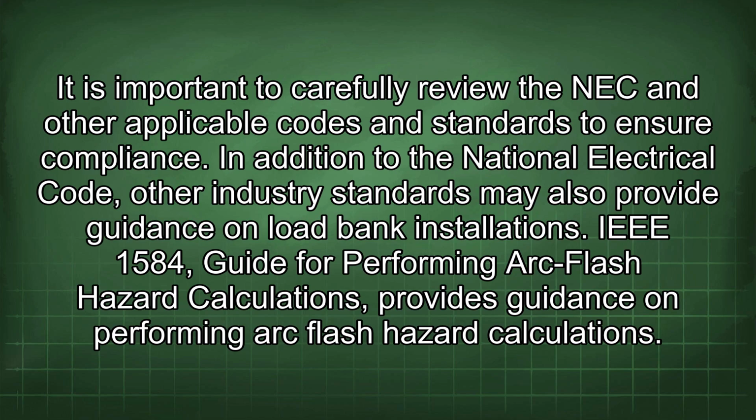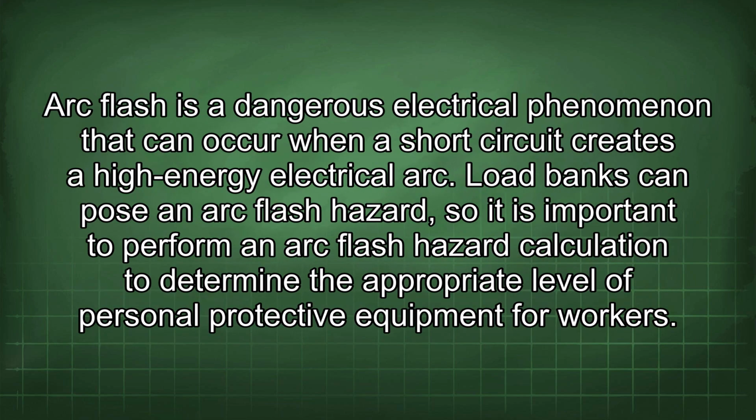In addition to the National Electrical Code, other industry standards may also provide guidance on load bank installations. IEEE 1584, Guide for Performing Arc Flash Hazard Calculations, provides guidance on performing arc flash hazard calculations. Arc flash is a dangerous electrical phenomenon that can occur when a short circuit creates a high-energy electrical arc. Load banks can pose an arc flash hazard, so it is important to perform an arc flash hazard calculation to determine the appropriate level of personal protective equipment for workers.